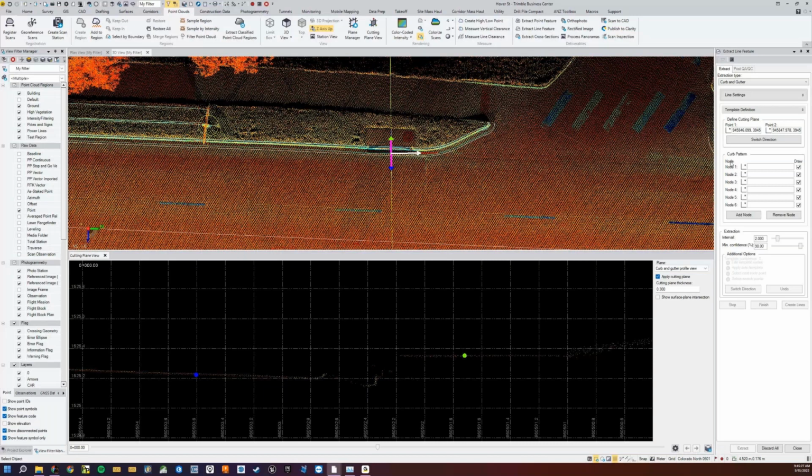So something like a curb, the areas where that's going to happen is, you're going into an ADA ramp and it starts to taper down. I want it to just stop as soon as it's a little bit off. I'll adjust my template for the changed height of the curb for the ADA ramp, extract across the ramp, go back up to the next section of the curb, and then continue extraction with my normal template.